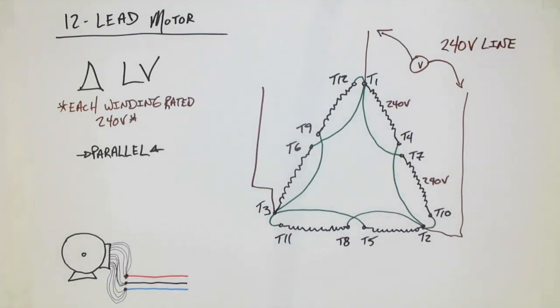So there you have it. One motor could be connected to 3 or 4 different 3-phase voltages depending on where in the world it happens to be used. These are the most common 3-phase stator connections that we are going to see, and they are the same types of connections for different types of alternators, synchronous motors, wound rotor motors, and SCIM motors.